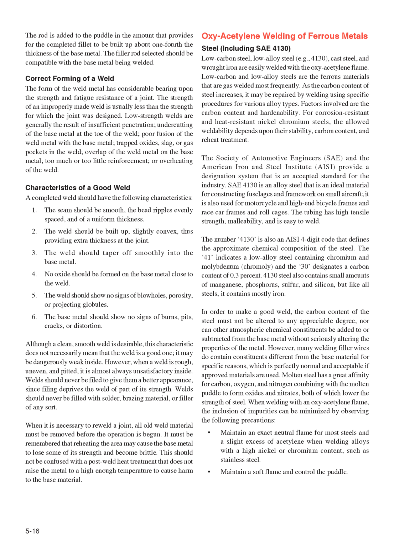It must be remembered that reheating the area may cause the base metal to lose some of its strength and become brittle. This should not be confused with a post-weld heat treatment that does not raise the metal to a high enough temperature to cause harm to the base material.